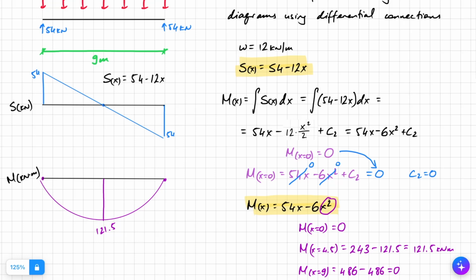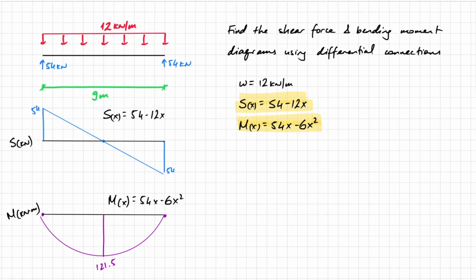We can also see, as we know from before, that when the shear force passes through 0, then the moment is at the maximum. Now in this case it is symmetric, and so we know exactly where that location of maximum is. But say we didn't, we can find it out easily, and I will show you how next. So say I wasn't too sure where the maximum moment was. So we'll start off by finding the location of max moment.